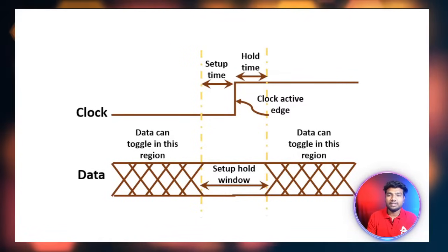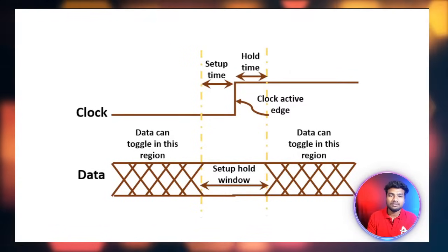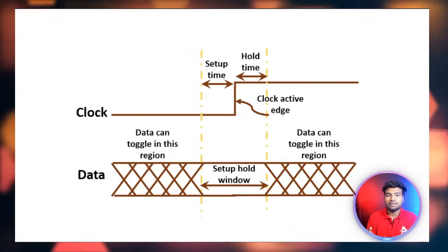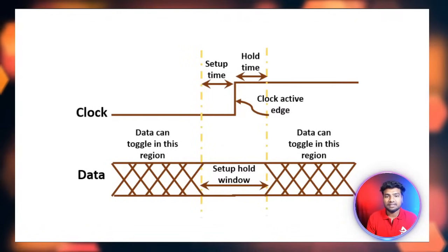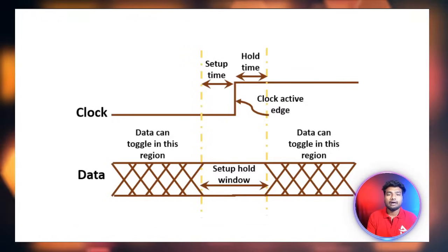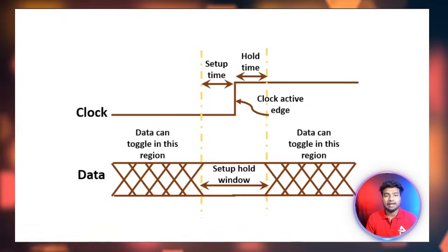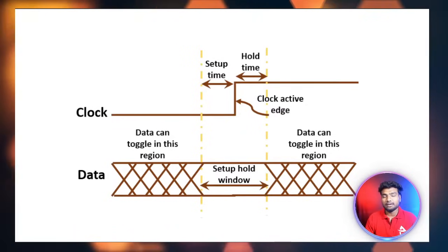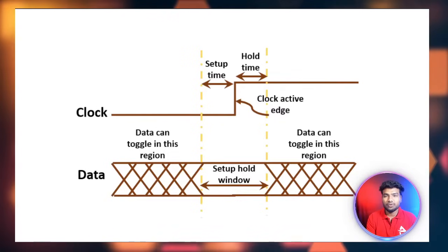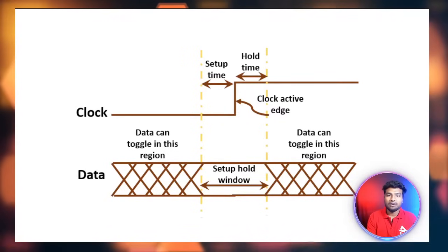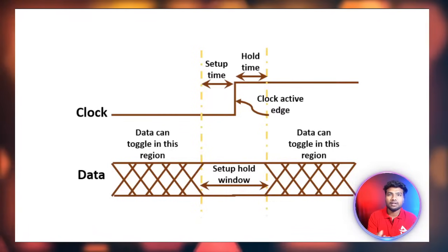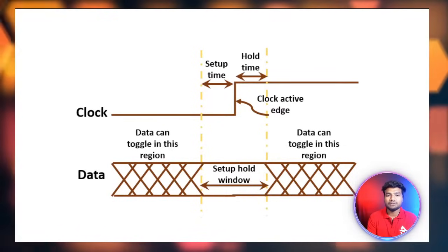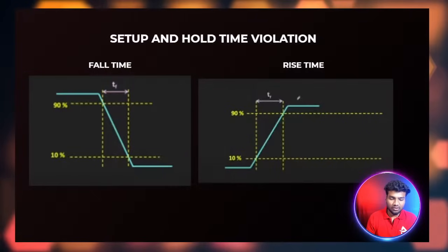While writing the Verilog code or dealing with sequential logic, most signals depend on signal transitions, and signal value assignment fully depends on clock pulses only, clock posedges or clock negedges. So if you take a posedge of the clock, before the edge the signal you are dealing with must be stable. It looks like this.